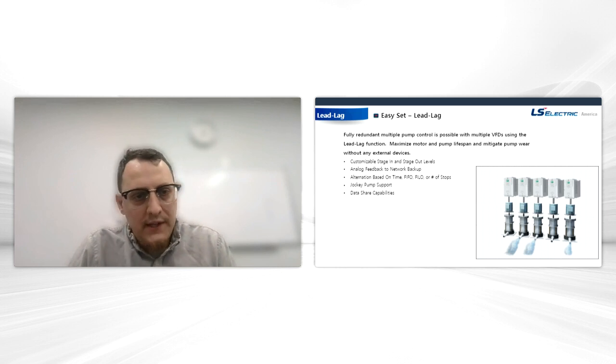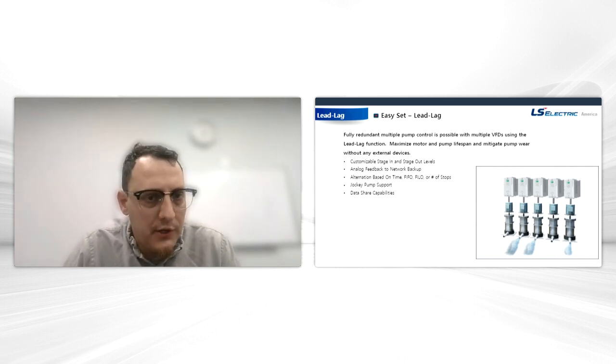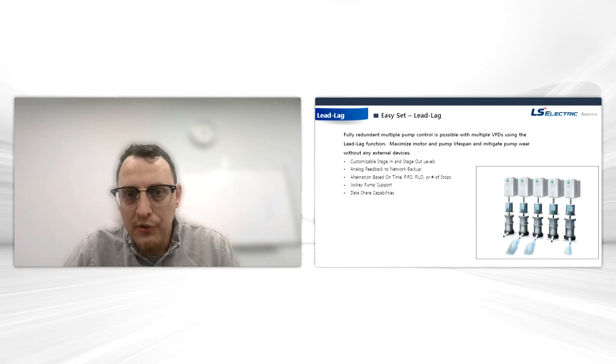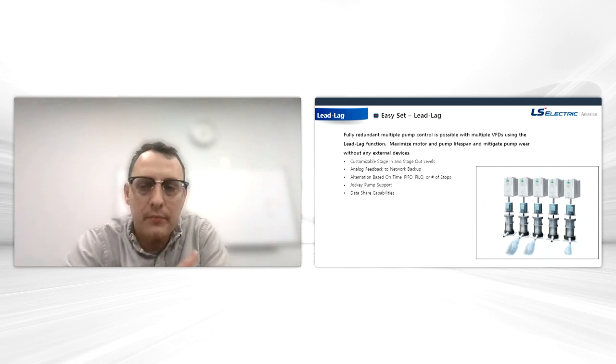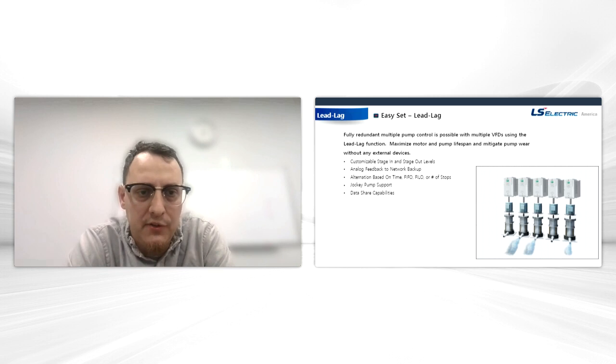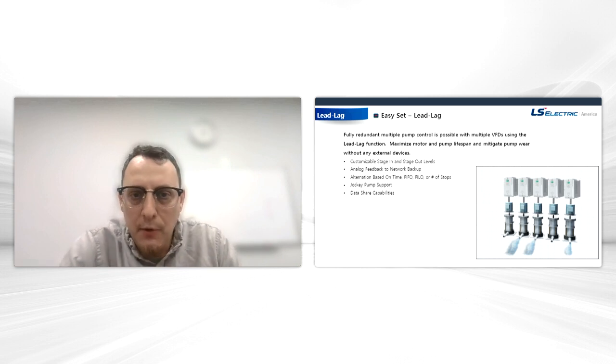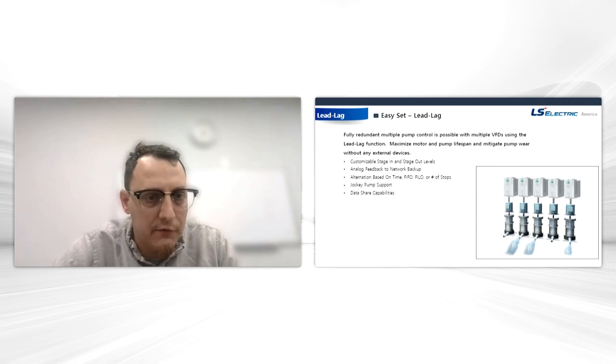What lead lag is, is a fully redundant multiple pump control system. And it's possible by using multiple VFDs that are all set up for the lead lag function. In our case, we use the macro. The main benefit of this is you can maximize the motor and pump lifespan and mitigate pump wear, and you don't need any external devices. Really, the only thing you need is a couple of wires between the drives and at least one feedback device.